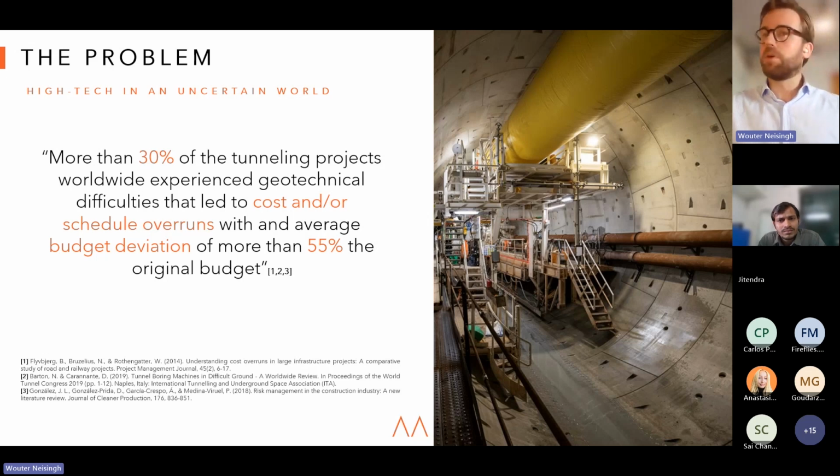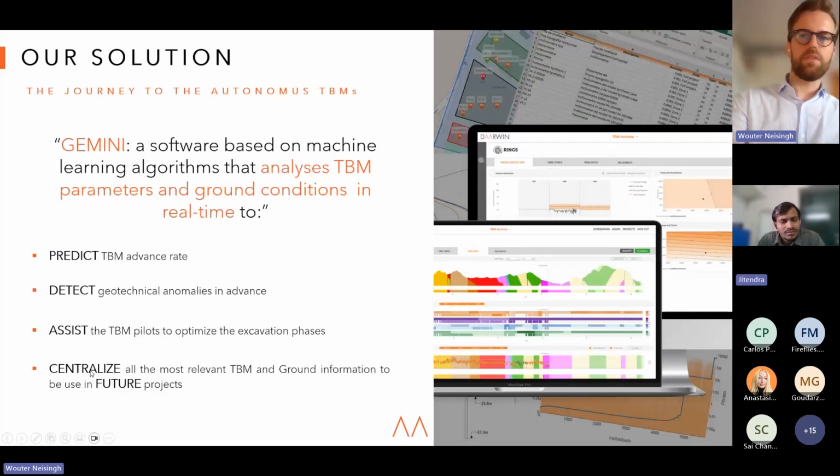And that poses a challenge, right? Just like we see in our construction industry. Now, what we developed is a tool where we do a few things. We predict the TBM advance rate. We do that in real time. Then we detect if there are any geotechnical anomalies, and we assist the TBM pilots to optimize the excavation phase.